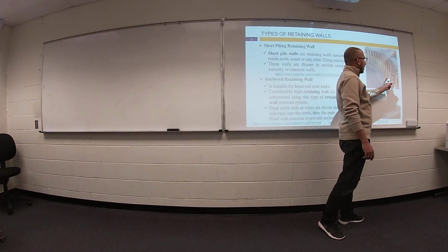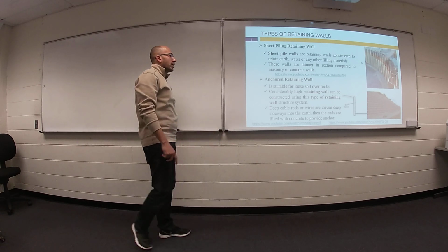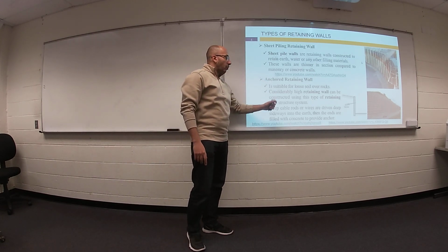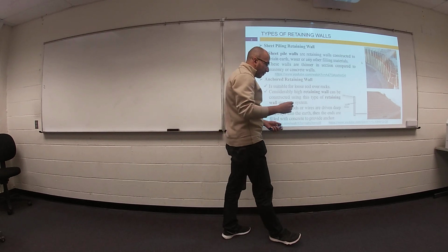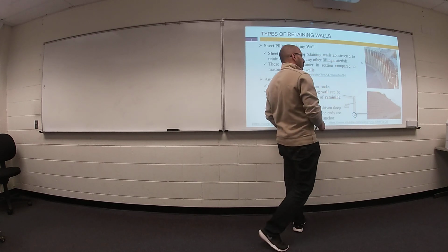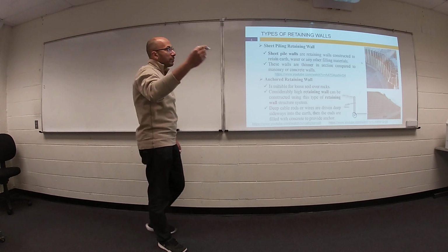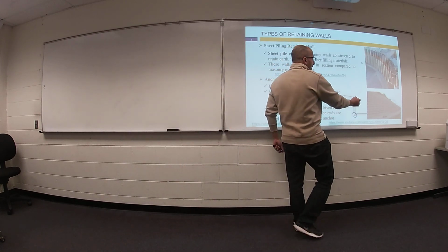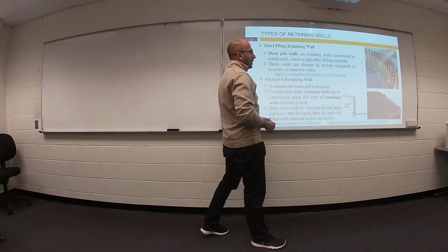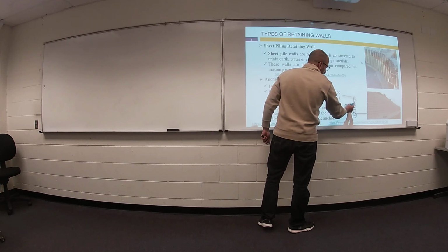A steel cross section interlocks to each other to make this fence around your excavation. The fourth one, which is called the anchored retaining wall, actually we don't have enough depth embedded in your soil to make fixation for the retaining wall, so we need to provide another support at any location through the height of the retaining wall. So we can provide an anchor embedded in the soil.